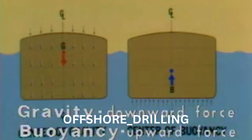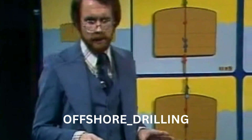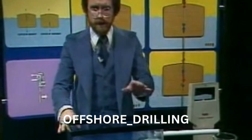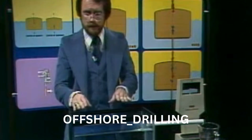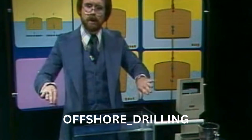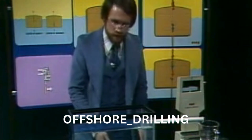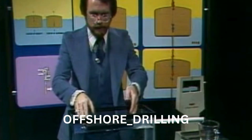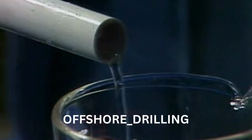The displacement of a vessel is the weight of water that the vessel pushes aside or displaces when it is floated in water. Let's take a look. Here we have a tank that, as you can see, has been filled to capacity with water, so that if an object is placed in the tank, some water will be pushed aside or displaced and will be collected in the beaker. We're going to take a block of wood, which will symbolize a vessel, and float it in the tank. As you can see, the vessel pushes aside or displaces a certain volume of water.